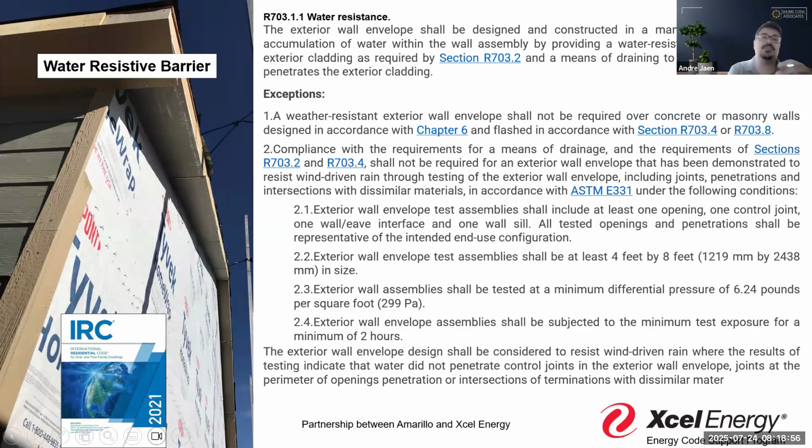Well, that ties directly to the drying effect there, right? If it can drain out of the assembly, that means that the assembly can get airflow to dry off while still preventing penetration into the rest of the building. That's why your water resistant barrier is going to tie very neatly and very importantly to your exterior wall coverings and your flashings, right? Because those are all going to work together to create that continuous weather water resistive barrier that's described in 703.11.